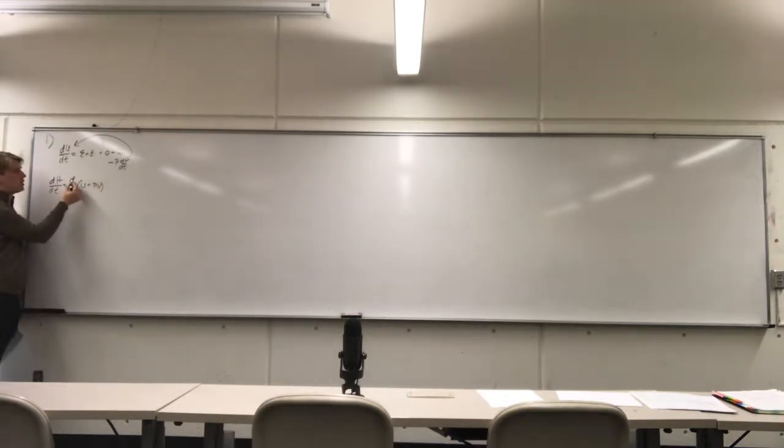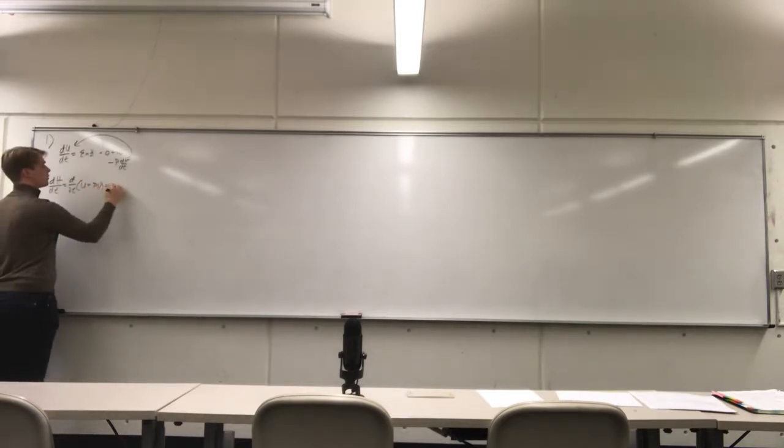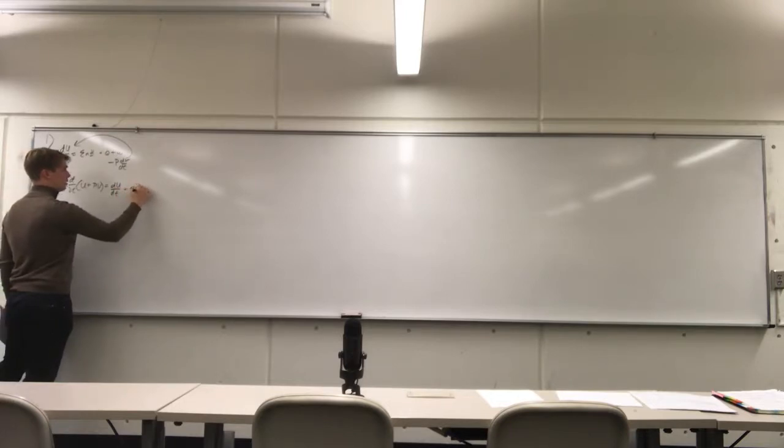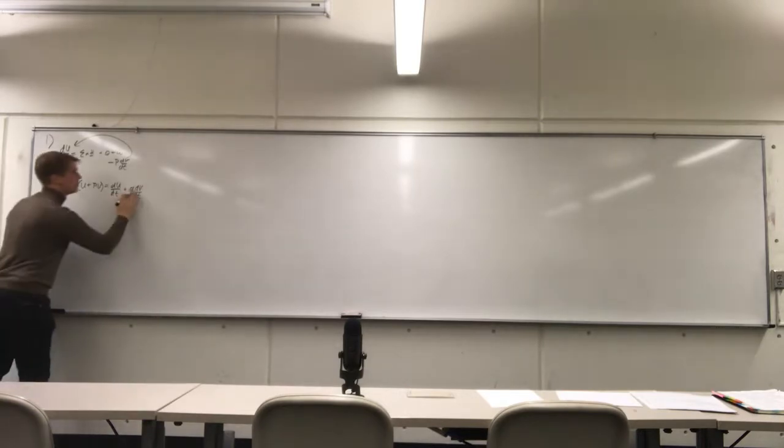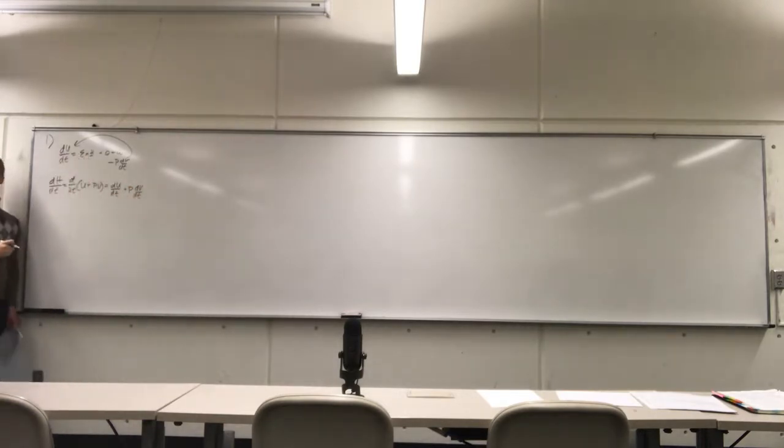Now, if we take this expression d/dt and we distribute it, we have du/dt, and then we have P dV/dt. Now, we don't have to do the chain rule, product rule on this one, because we know pressure is constant in this apparatus, right? So these expressions are equivalent, right? Moving this over to the other side, which is the same thing as writing dH/dt. We've had a couple of examples on the homework illustrating that for a closed system at constant pressure, enthalpy is the term we want to use.